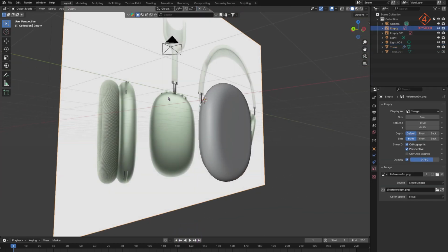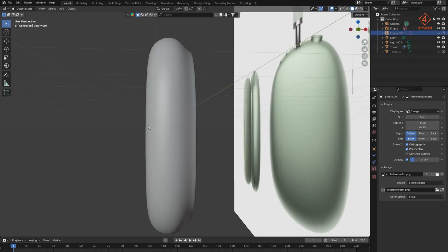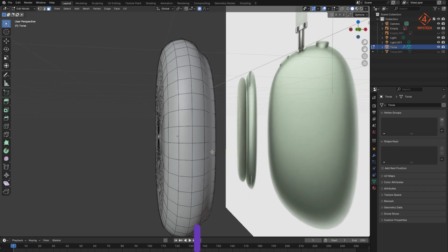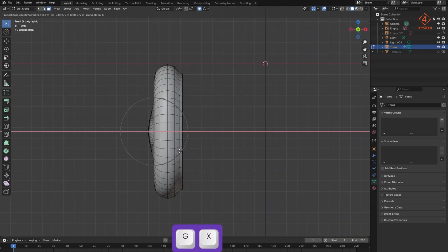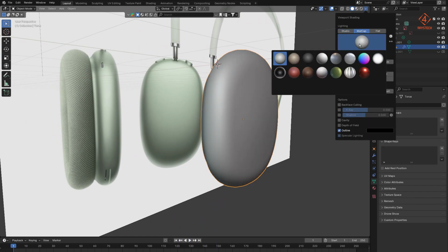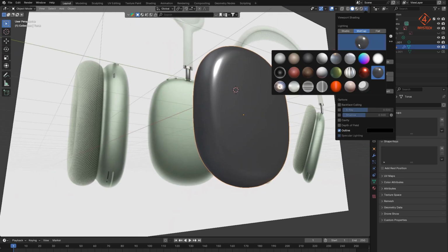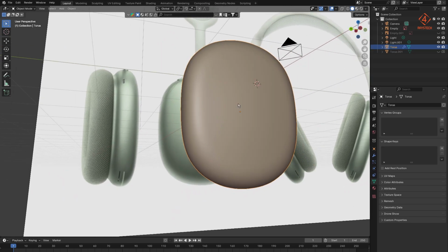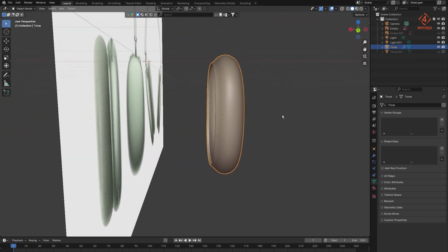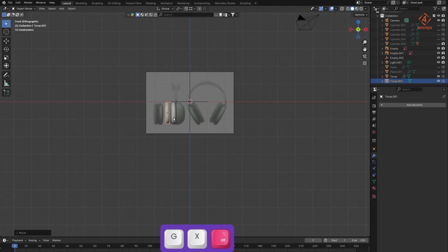If you notice this AirPods Max, it has a certain roundedness on its outside, so we want to create that roundedness. We can either use the bend tool, or we can do it just by proportional editing. We can create that little bend on the outer part of the surface. It's looking good now. If I turn on the matcap you can see how the surface looks applying different matcap settings. We can see how smooth, shiny and clear the surface is. You can always reference these different settings to see how the surface is looking. Okay, let's move that back in.